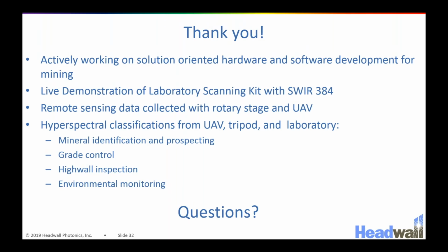If you hear that little hum right there, that's the Stirling cooler keeping the focal plane at 150 Kelvin. We do not cool our spectrograph, and actually cooling the spectrograph is probably what costs you a bunch more energy on the NEON system. We don't do that because of a SWaP problem: once you had a cooler that would cool the whole spectrograph as well as the focal plane, it would be too heavy to fly in one of those drones.